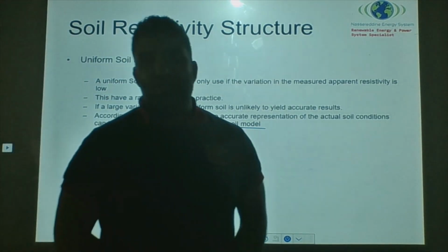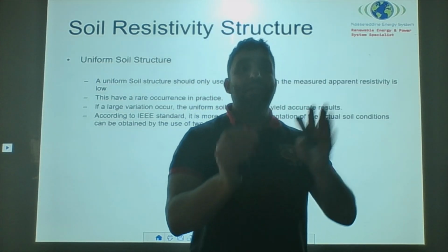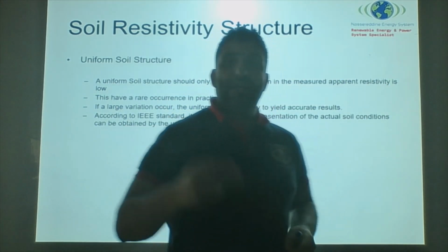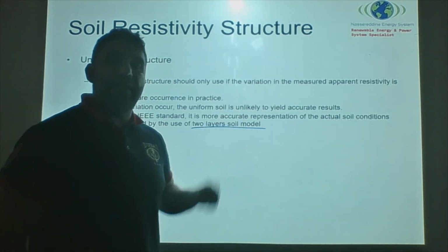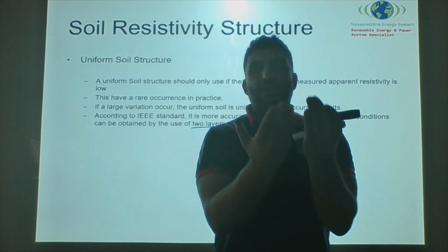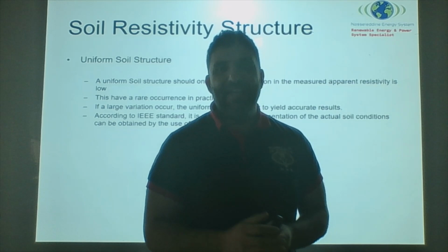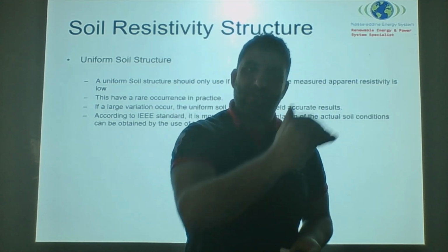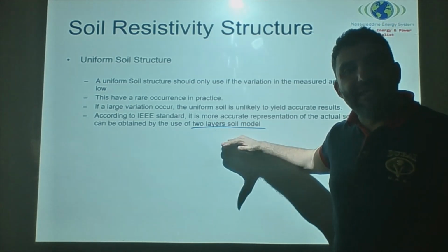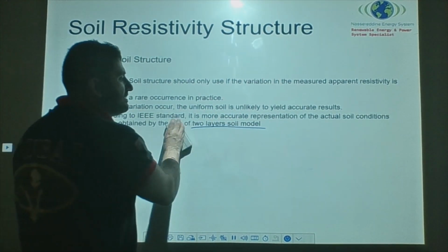So as a project manager from any discipline, computers, electrical, civil, mechanical, management, you don't have to be an electrical engineer project manager. After you see this lecture, all you have to do now is pick up your earthing report. Make sure they provide you with the table of the field test. If there is a major variation in the result and they used uniform, tell them that's against IEEE recommendation. Please change it.